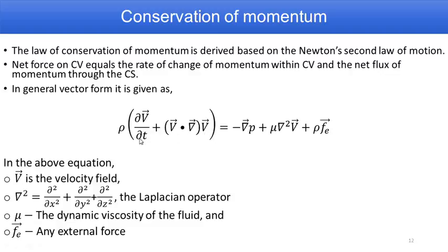So the left hand side is acceleration and on the right hand side pressure is a force, viscosity is also a shear force, or any other force. Okay. So that is why I said Newton's second law, F is equal to m into a, is the first principle based on which the conservation of momentum is derived, and you are able to see here the same acceleration terms and force terms on the other side.